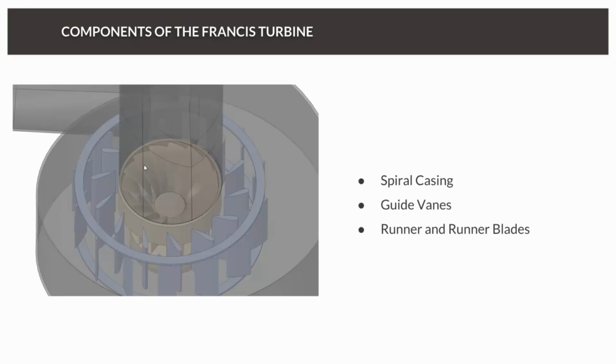And that's where CFD can help too. Initially, there's no way that I know of that we would know what kind of angle to have those blades positioned at. You could do it through test, of course, but with CFD, we could optimize that before we built anything. And then from there, the flow moves into the actual Francis turbine in the center. The other thing I think that's useful to use CFD for is the design of the draft tube at the outlet. What we need to make sure we do is expand the fluid gradually without any recirculation.